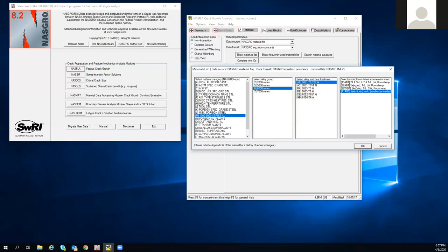Even still, whenever you have hardware that's built, the raw stock of the material will come with material certificates of conformance, which come from the forging houses or the metallurgical houses that provide that material. They have to provide data showing that this aluminum meets these requirements. It has these minimum strength, elongation, and fracture toughness properties that at least make sure that you're analyzing to the correct values.